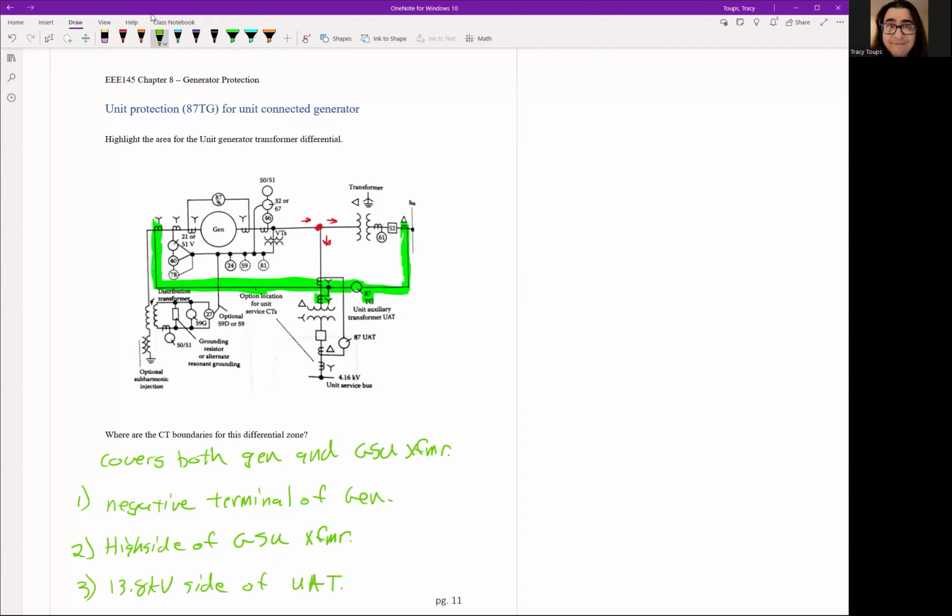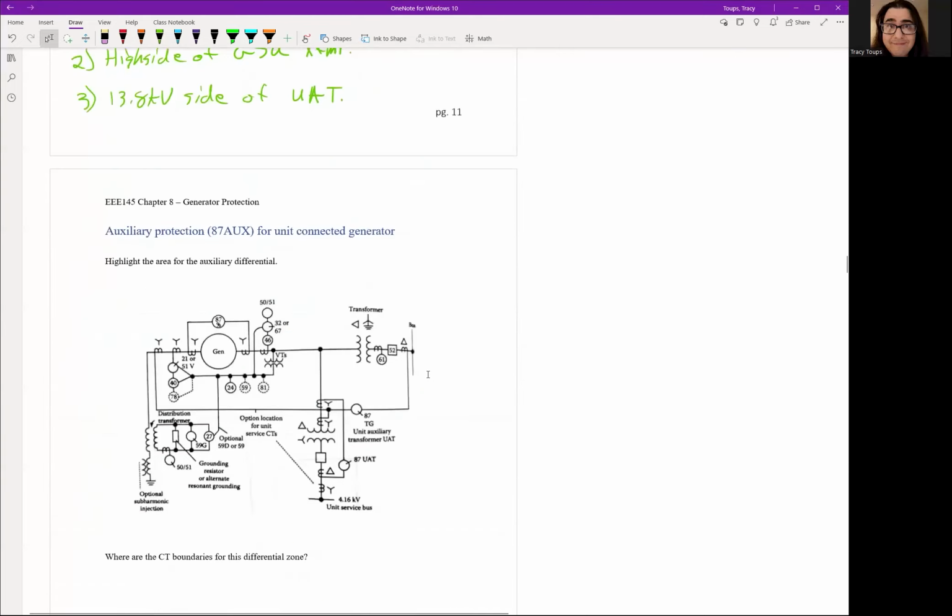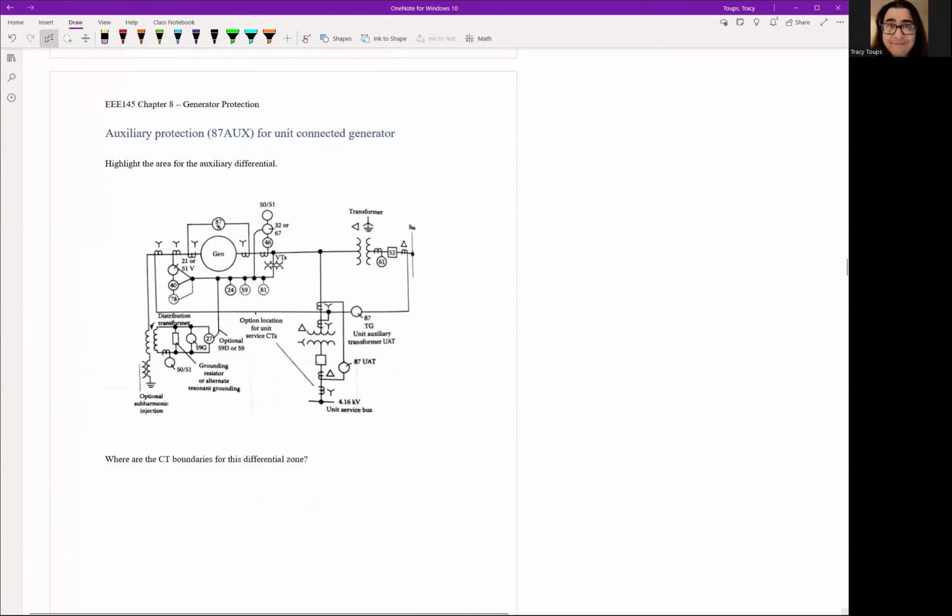Okay. So again, this is another big loop. And this one, as you see, also protects the generator. So right now the generator has 2 differential relays on top of each other, which is expected because, again, the generator is by far the most expensive device on the power system. So we need to make sure we protect it adequately.